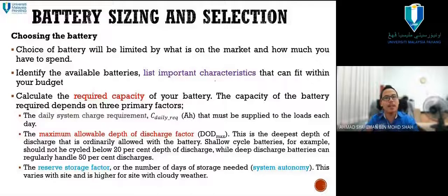The capacity will multiply. But for the panel itself, for example, you use 100 watts but your battery capacity is 100 Ah. How can it charge? No, it won't have time. While charging, you are also using. It really won't have time. However you design it, however much money you pour in, even using a 1 horsepower aircon to look impressive, at the end, if you don't have this kind of knowledge, it's a waste. So I hope after this class, we are not going to make that mistake.